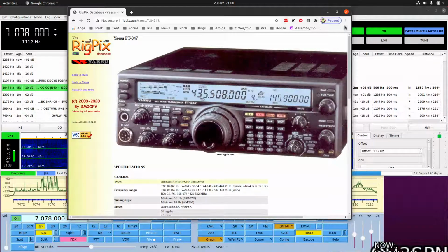It's great for voice. For voice, it's perfect. The audio is punchy. Everyone says the ICOM 7300 must use a condenser mic, must use an electret mic. Do not use a dynamic mic. You end up having the mic gain on 100%, and you've got all these settings boosted up, and compression enabled at a higher level, and just do not do it.